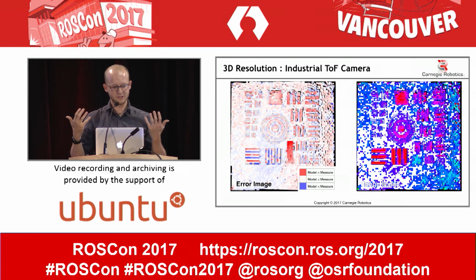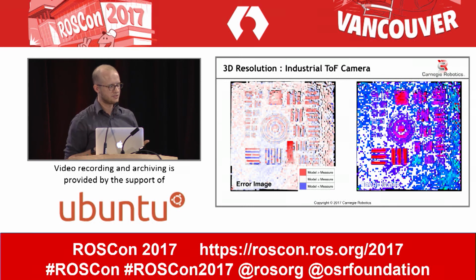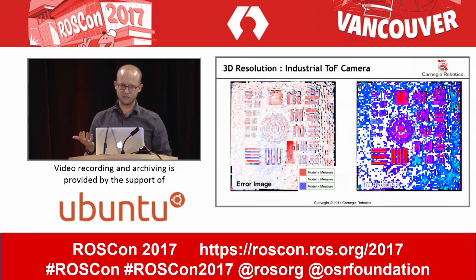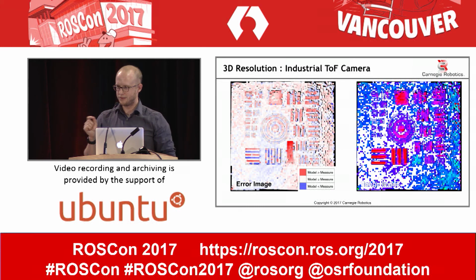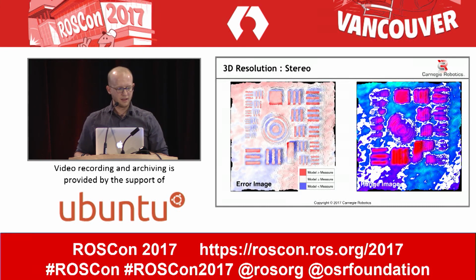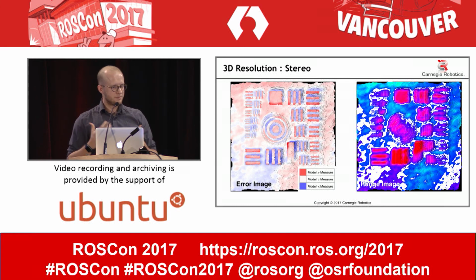You also see that there's sort of equal performance of this camera both horizontally and vertically, but it's relatively low resolution. Even these large targets only have about 3 pixels of data on them, and then you can see the whole top left corner, the very small features, completely blend into the background. They don't have enough size horizontally or vertically to be visible, and the depth accuracy of the camera can't pick them out either.